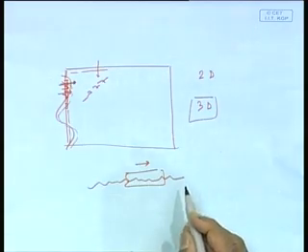So in the first case, the 2D case, I usually get a larger response, for example larger heave, or in the case of beam seas, larger roll. Therefore, if a ship is designed to survive a 2D spectrum, it would normally fare better in a 3D spectrum. After all, you are going to design the ship for waves coming from all directions.